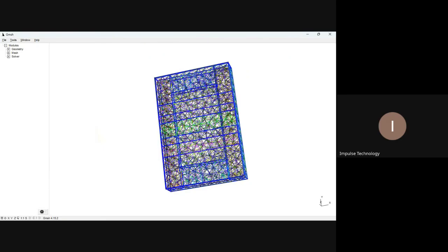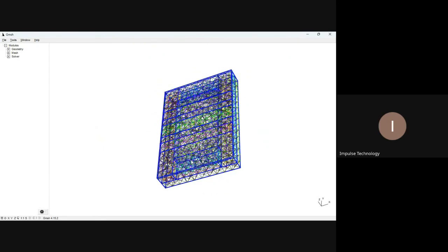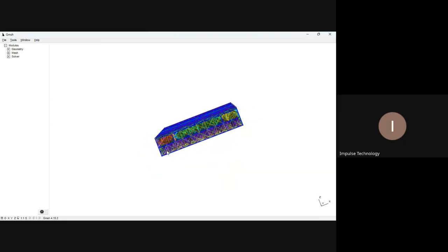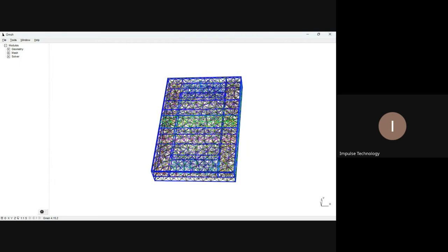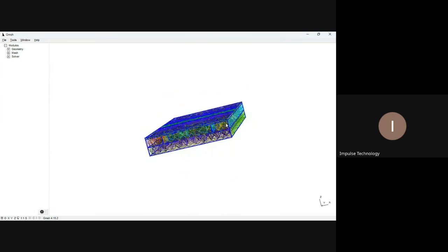Here you can see the fully depleted silicon-on-insulator. First, this is a 2D layer at the bottom. After that, we create an oxide layer, then the silicon thin film layer, then the top oxide. After that, we introduce some gates here and create a 3D mesh structure.